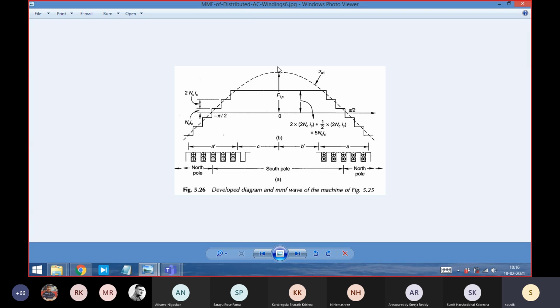Again, let us pause and think. Rotor coil current is not at the same frequency as the stator coil current, but the magnetic field created by the rotor coil current is synchronized with the magnetic field created by the stator coil current. This you understand or not? If you don't understand, please feel free to tell me.